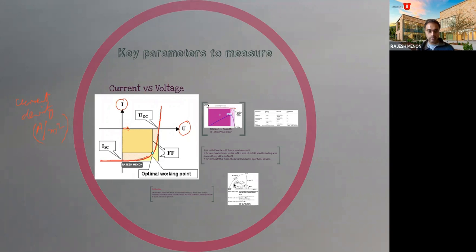And that's because you're getting this minority carrier injection that's happening. We'll talk about that on Tuesday. The current increases until the current actually becomes zero. Current is zero means it's open circuit, so this is referred to as the open circuit voltage. That's what the OC stands for. And after that, it becomes forward bias. You have majority carrier injection, and you get current essentially exponentially increasing.